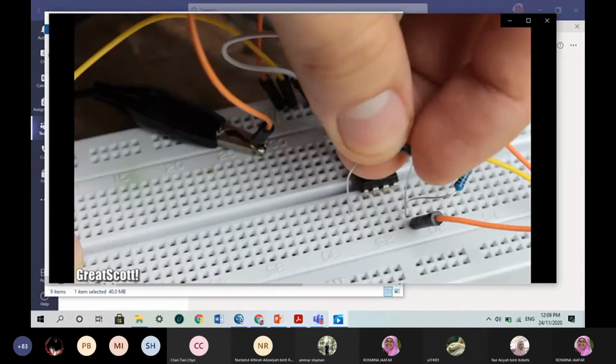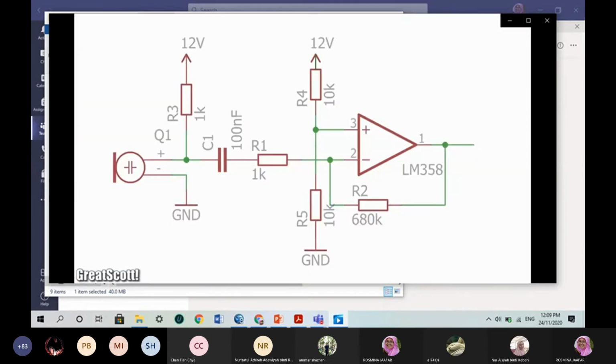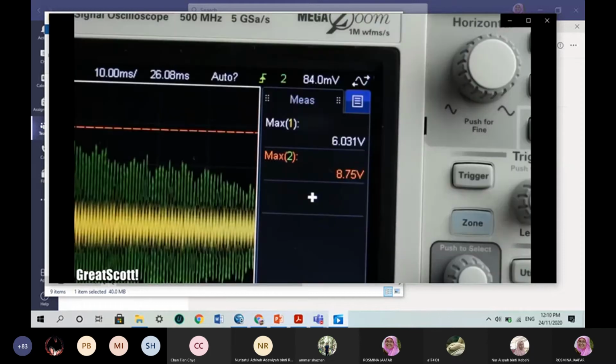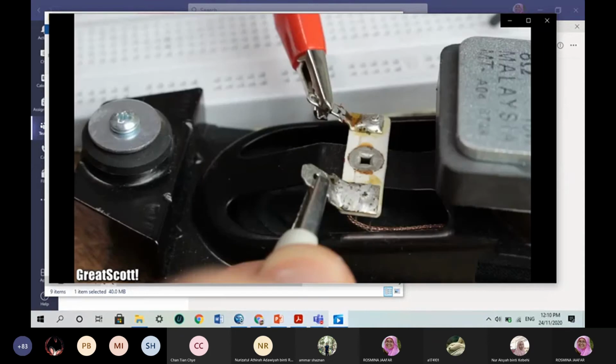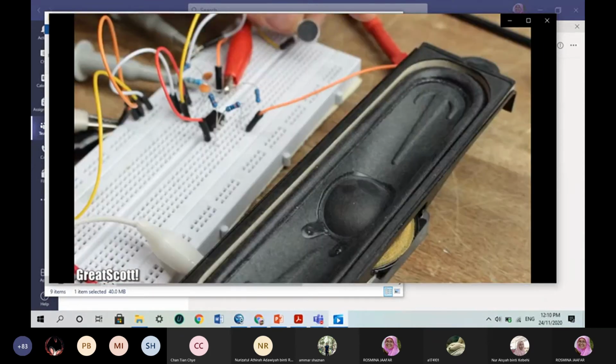This results in the classical formula for the inverting op-amp circuit. And by connecting the plus input to a DC offset voltage instead of ground, we can amplify the microphone AC signal completely without amplifying any DC voltage. The output signal can then be connected to a speaker, but just like I said before, because of the small maximum output current, the sound is almost unhearable.